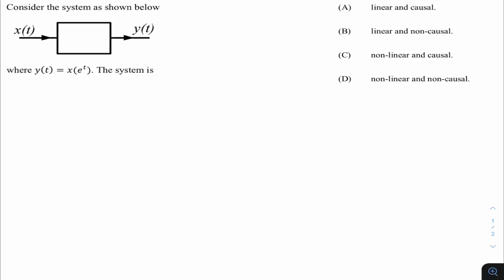Regarding the linearity, if you observe this expression carefully, no manipulation is done with respect to amplitudes. The manipulation is done with respect to time. So there is no question of it being non-linear, right? Because if we are only manipulating the time, nothing on the amplitude side, why would it be non-linear? There is no chance at all. So the system is linear. Otherwise, you can go by testing the homogeneity and additivity. Okay, we'll do that also.